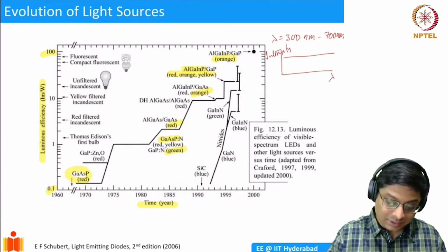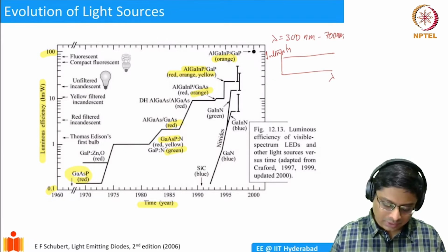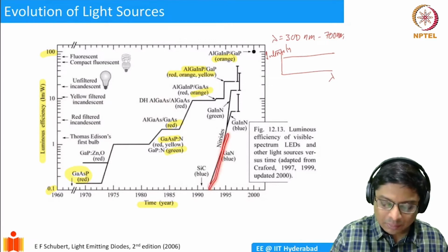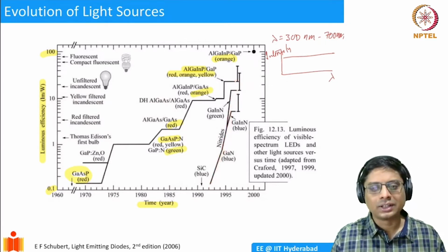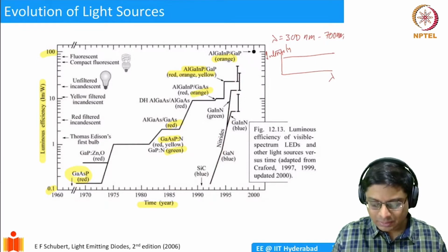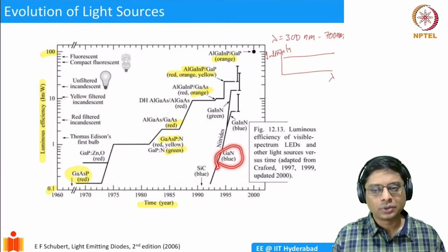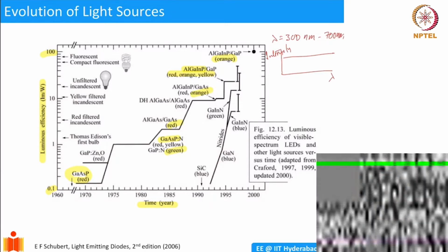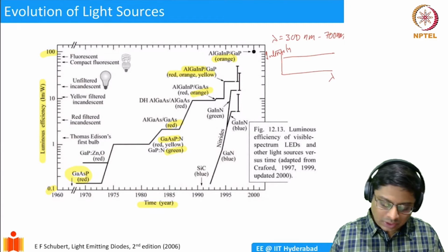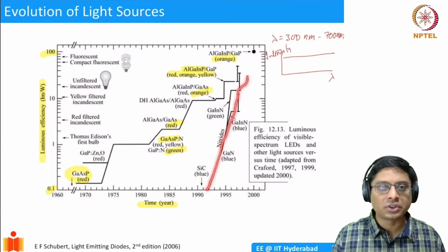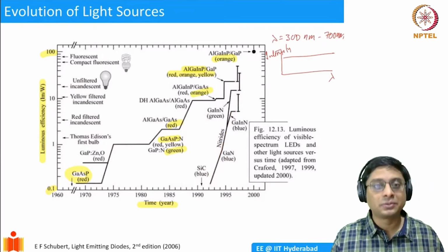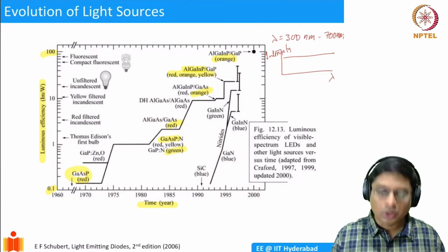The other important trend you see is that starting about the 90s, there's a very significant development of nitride semiconductors, starting with gallium nitride, which has a band gap of 3.3 eV. So it can be tuned to give you emission in the blue spectrum, and sometimes even in the green spectrum. These nitrides give very strong emissions, and they are developing significantly. A Nobel Prize was given for the invention of the blue LED, I believe in 2014. So there's a lot of improvement.